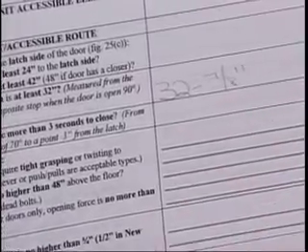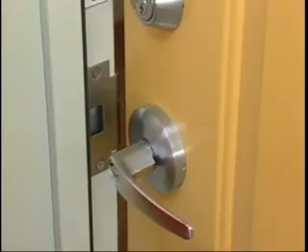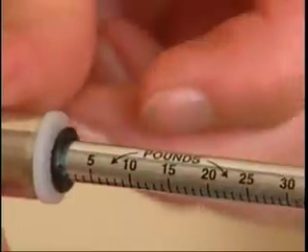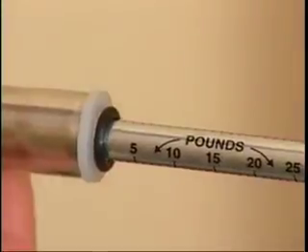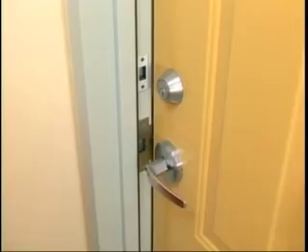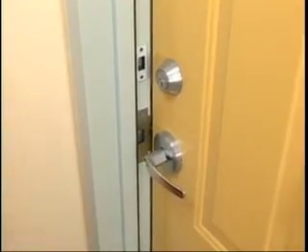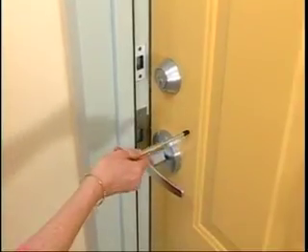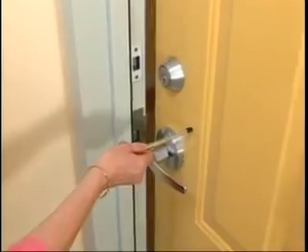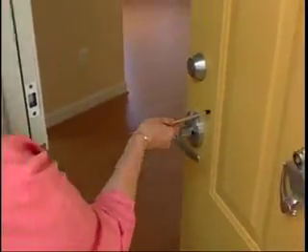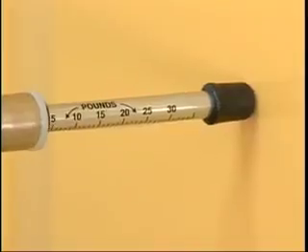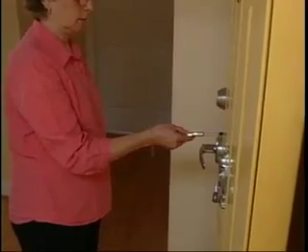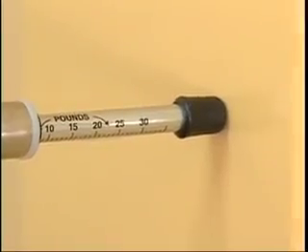Next, we are going to measure the pressure of an interior door using the door pressure gauge. Take the gauge and make sure the black O-ring is pushed against the instrument's flange, starting at 0. Open the door about 3 to 4 inches, and place the door pressure gauge on the door around the location of the door lever. Push the door open with a steady flow of pressure till it is opened approximately 90 degrees. Look at the gauge and record the pounds located at the bottom of the O-ring.